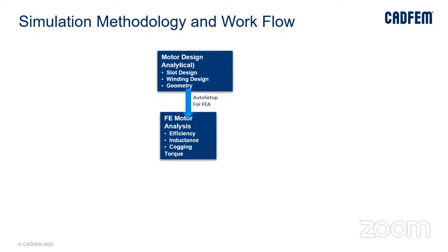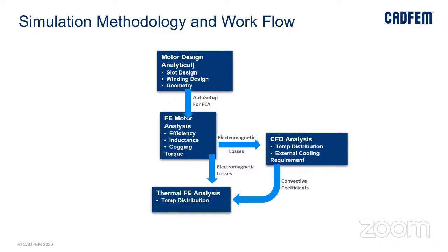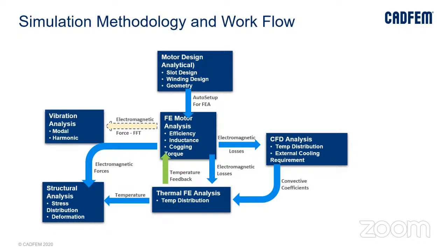The finite element methodologies will take it to the next level, like the multiphysics environment, to understand the multiphysics challenges. And finally, you can also take those electromagnetic solvers to computational fluid dynamics analysis, and to the structural analysis to understand the vibration behavior of the motor, or any other components. So the same funda is going to be applicable for the remaining electromagnetic components.